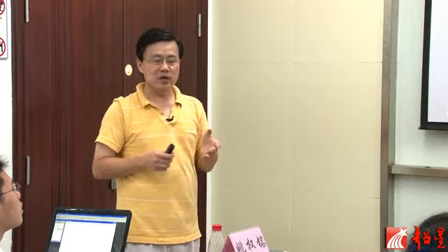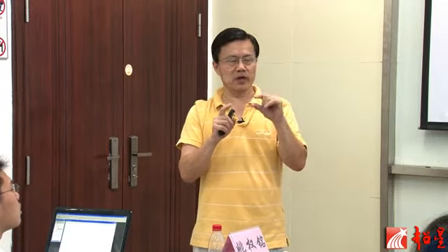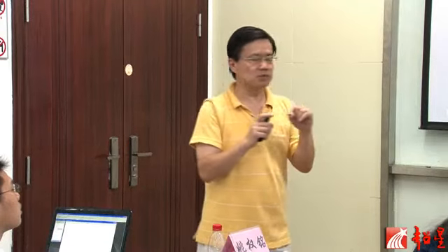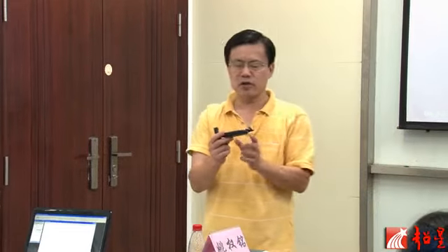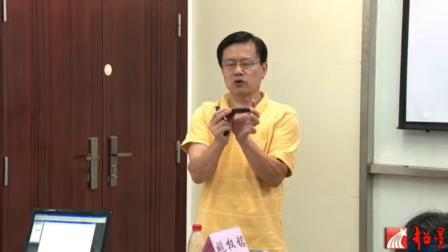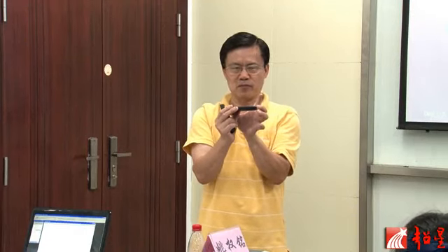Remember, for 3 gigahertz the wavelength is 300 divided by 3 gigahertz, so 10 centimeters. So if you design a board that transmits 3 gigahertz through this cell phone, it's about 1 wavelength long.